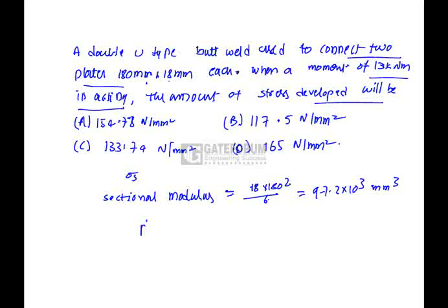We know that permissible bending stress sigma bf is 165 newton per millimeter square. We have to calculate the actual bending stress developed in this particular case.